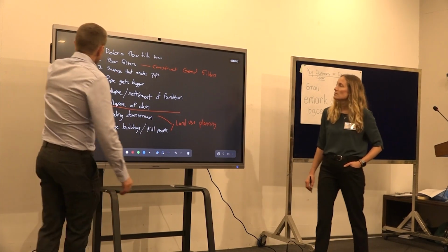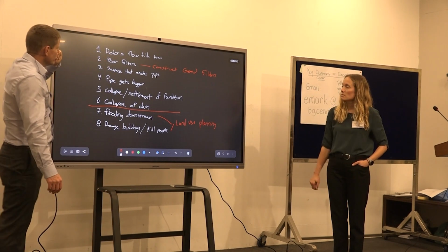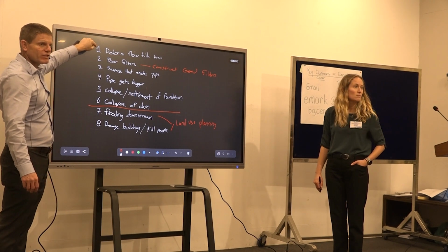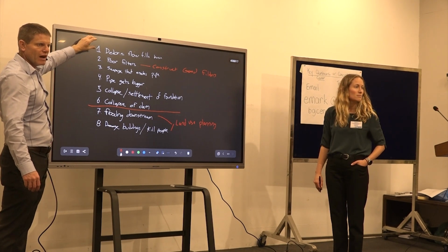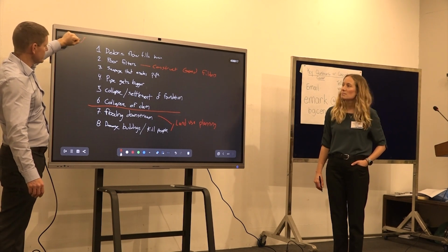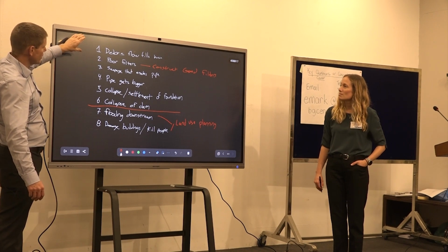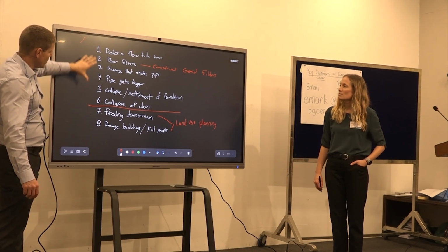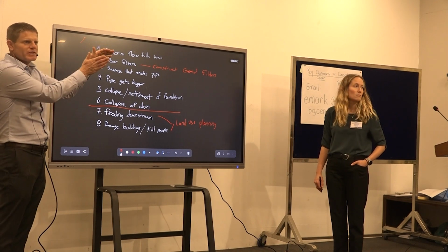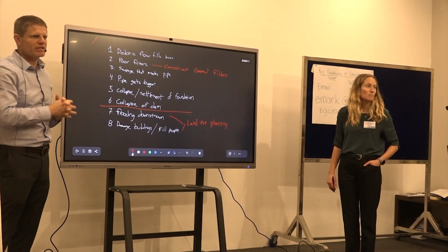Okay, so if we were to build a smaller check dam upstream, then that would stop this first item. Is that what you're saying? We wouldn't have the barrier filled. It will decrease the volume of debris in the main dam, I think. Yes, that would be possible. I agree. But I think maybe you would have the same failure mode potential just moved up to the first dam. So you would really have some of the same issues but at a different location potentially.